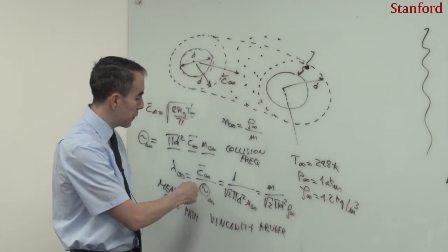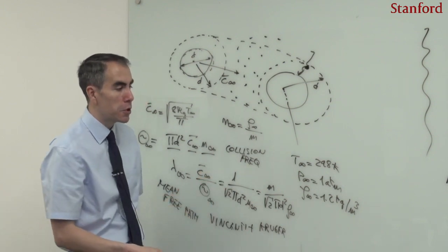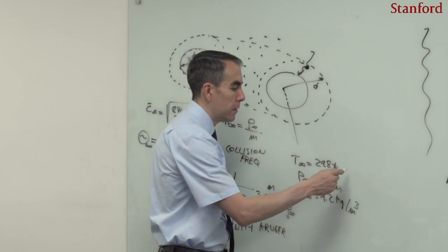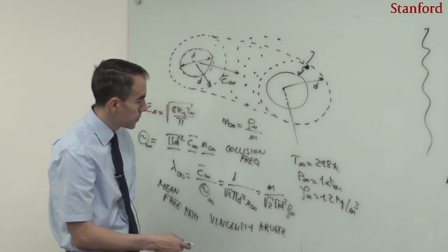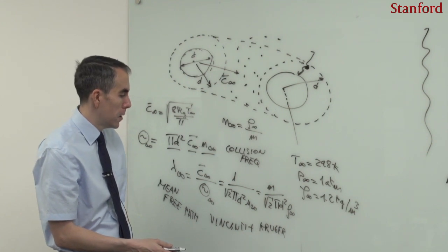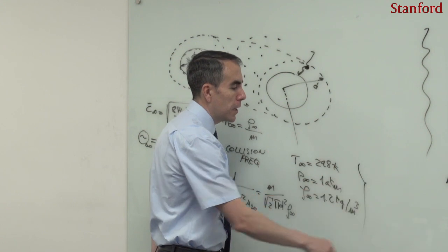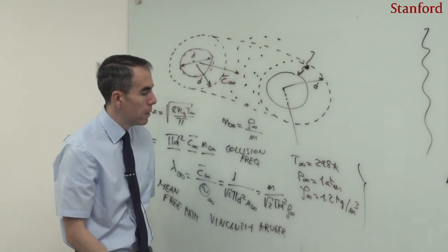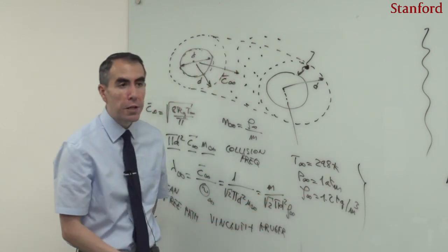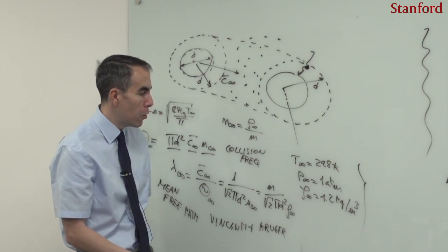The diameter of this molecule you could approximate as the diameter of a nitrogen molecule, for instance, that is tabulated. And I guess that's it. You wouldn't need anything else. And also you use the molecular weight for air, right, which is 29 grams per mole.